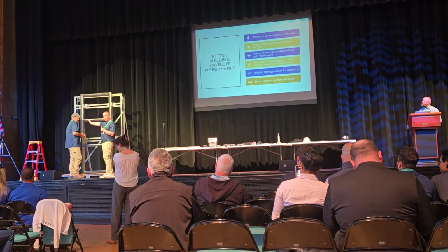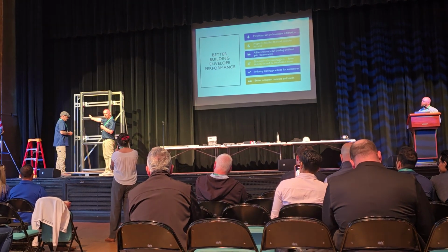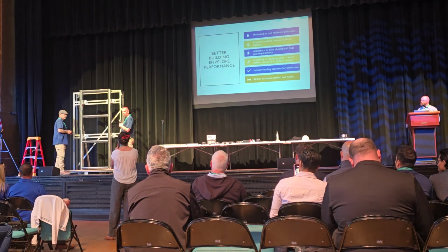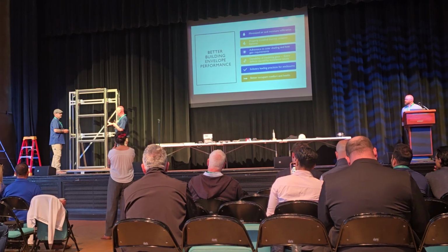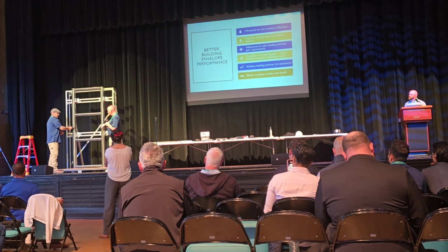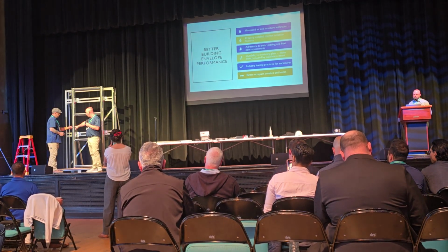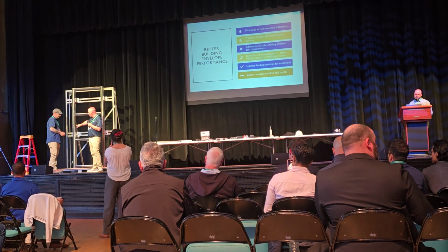This side, on the left-hand side of this framing, is basically a perimeter wall. Over here would be a continuation of the current wall, and so forth. But for training purposes and certifications, this is the rig that we have. So what we're doing is, all the steps are in the drawing. We have a half-inch minimum gap between the tubes.